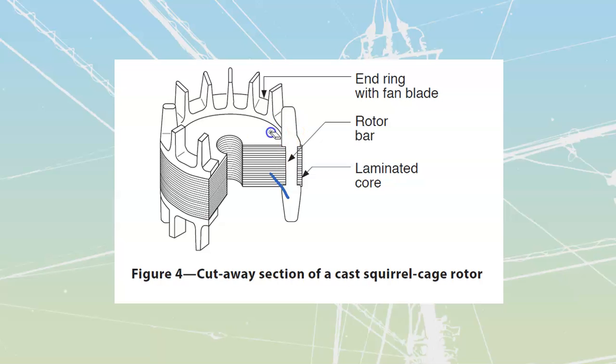The other reason that we have the steel inside the core, we talked about the fact that we want the high permeability and the low reluctance. Those are magnetic properties, but we're also going to want a fairly high value of resistance, because the actual aluminum is not insulated from the steel. But we know that our current is going to take the path of least resistance, which means it's going to go through the aluminum sections primarily. A little bit can go through the steel, but not a lot, because the laminations are going to slow it down, and it just doesn't want to travel through that high resistance path.